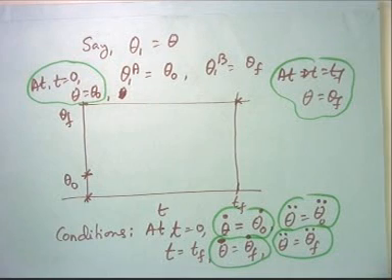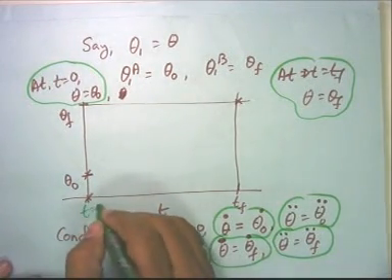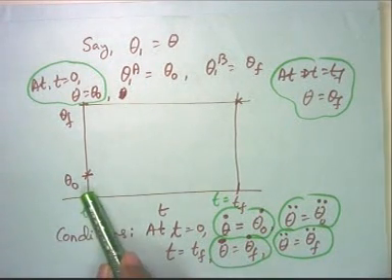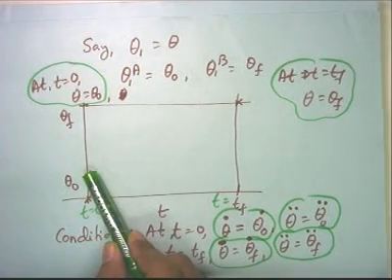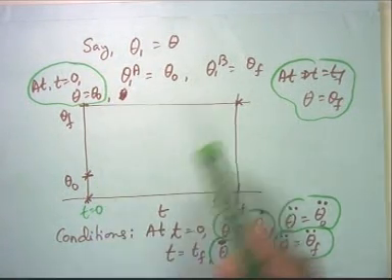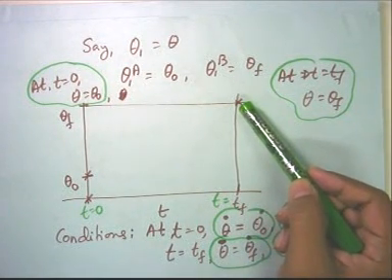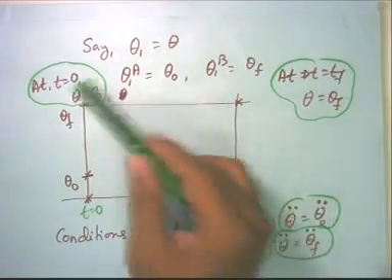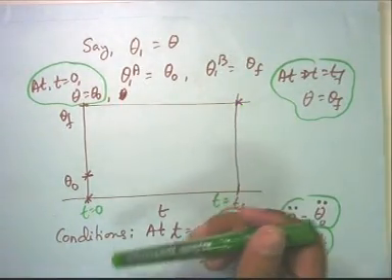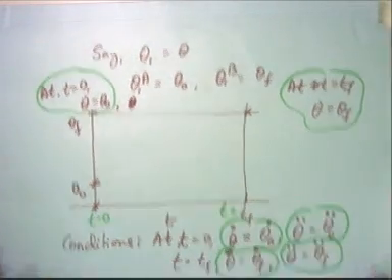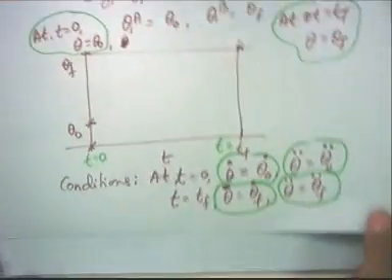So, you are putting 6 conditions. This is your t equal to 0 and this is t equal to Tf. I want my positions, velocities, acceleration as per my wish. Here also position, velocity, acceleration as per my wish. Now, such conditions can be satisfied using many different functions. But one of the easy functions would be a polynomial.